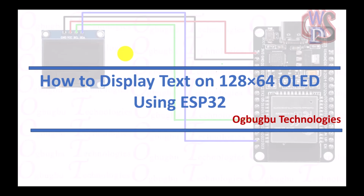But basically, I just want to put out there how you can do the proper wiring, because one thing about this OLED display, once it is not wired correctly, or the right libraries are not in place, nothing on earth will make it display anything. It is easier to interface them with Arduino even, because Arduino is way easier. The libraries are way easier compared to ESP32 or NodeMCU 8266. Any of these boards works perfectly. Whichever one you lay your hands on is fine. But today we're going to be focusing on the ESP32. So right now, let's just move over to the requirements.